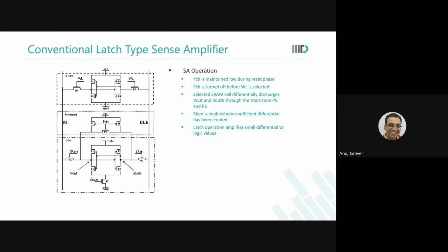Okay, thank you. You have seen the video, so you understood. But it also became evident that many of you have not watched the video in advance. Your choice. So what we are doing is that we are at the beginning, when the memory is all reset, the sense amplifier is connected to the bit lines, the bit lines are pre-charged to VDD, everything is hunky dory, sab kuch bilkul theek hai.